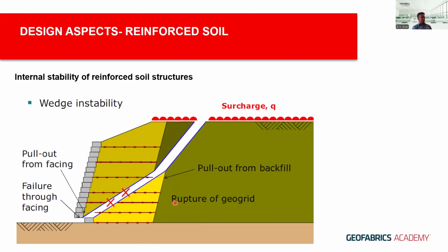The second part is that they are long enough to prevent pull out of the geogrid or the soil wedge due to slippage or shearing of the soil.